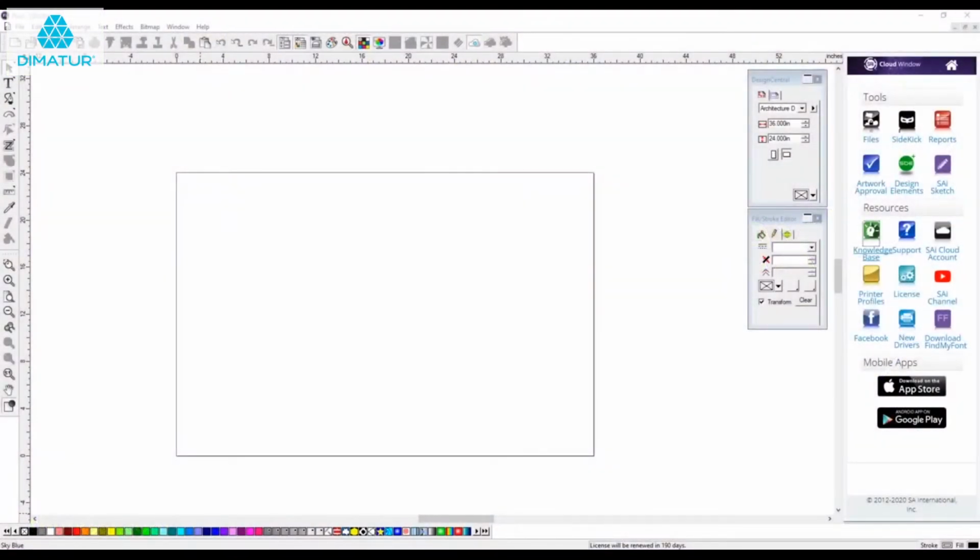Creating or editing text in Flexi is a really easy and user-friendly process. We can create powerful text options inside of the Flexi software that allow us to do all kinds of customizations. So to get started, we're going to go over here to our menu, and if you notice, this tool has a little black arrow at the top of it. That means if I left click and hold, a flyout menu will appear. Now we're going to talk about two main tools today, the text tool and the text on a path. But let's start with the text tool. If we click on this text tool in Design Central, this gives us a whole host of settings. So let's type up some text.